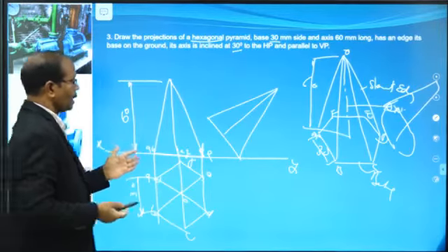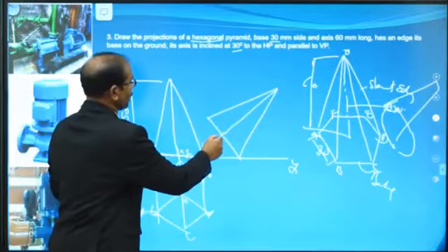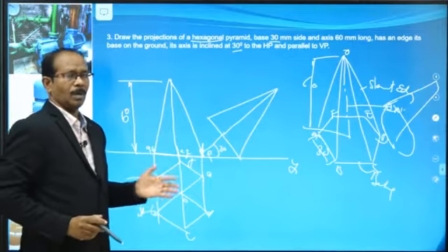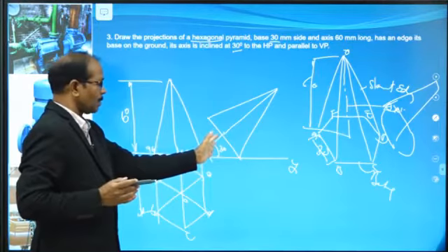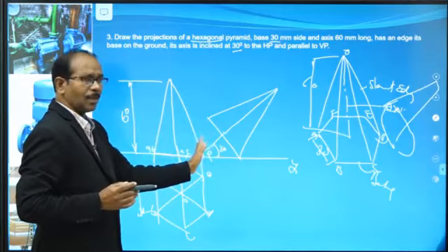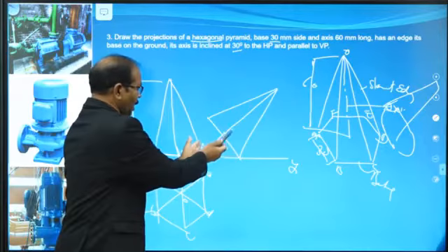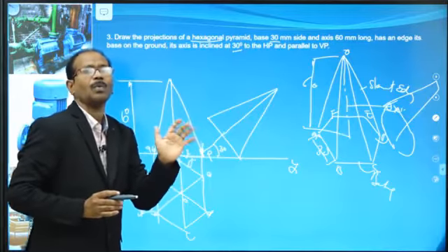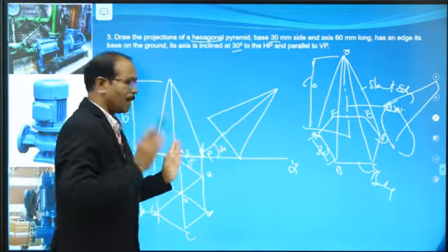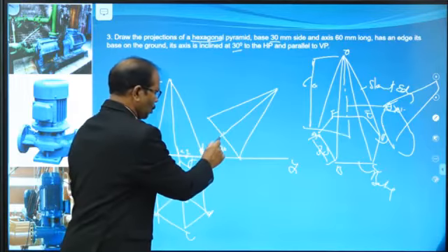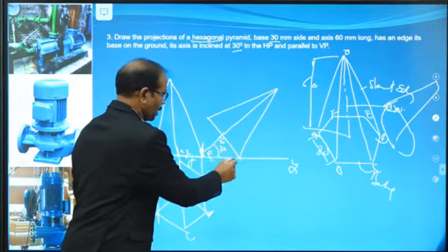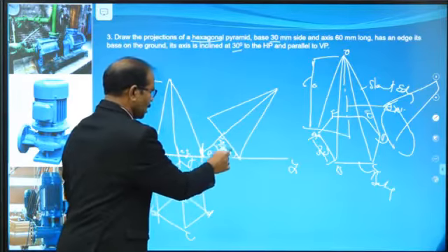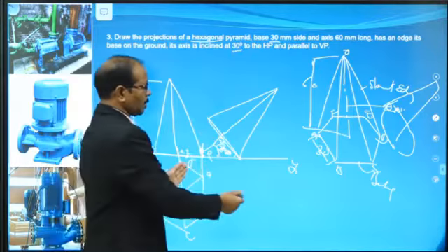How to draw this? At an angle, as he has mentioned, extend this one, making an angle of 30 degrees. How to draw this object? Let's apply the triangular rule in this one. In this way I can't draw it that easily, so I am introducing you to how to draw it easily. Just apply the triangular rule. Say this is the 30 degrees, now you know this is always 90 degrees. So because this is the 60 degrees, instead of 30 degrees, you start with the 60 degrees, and this line you can complete. Just observe how to draw.